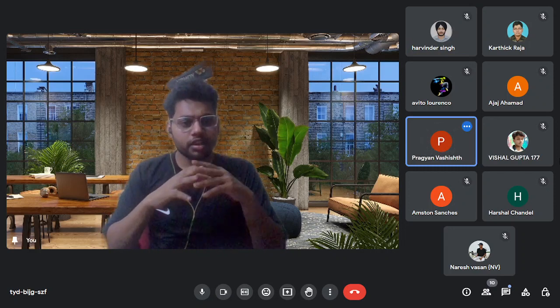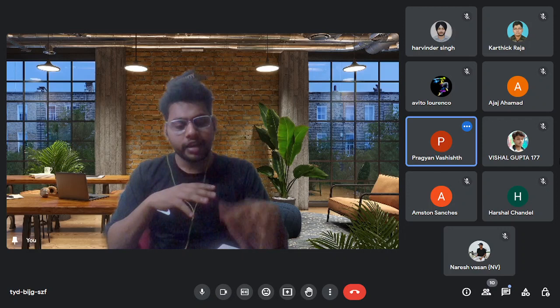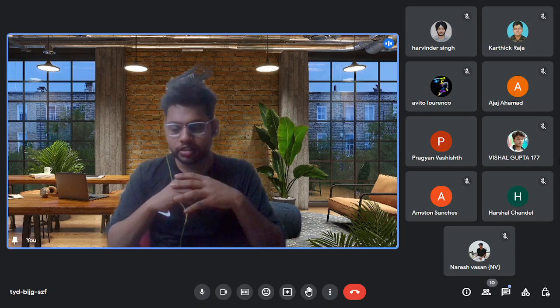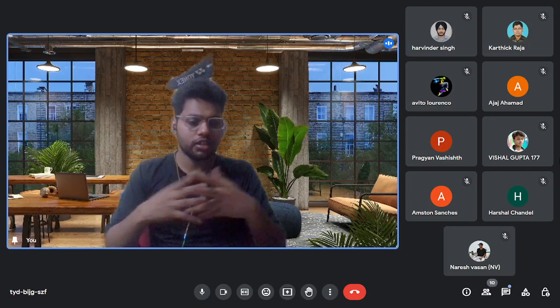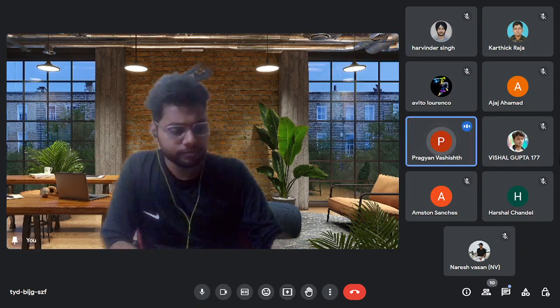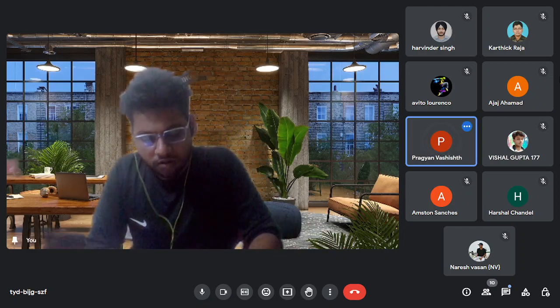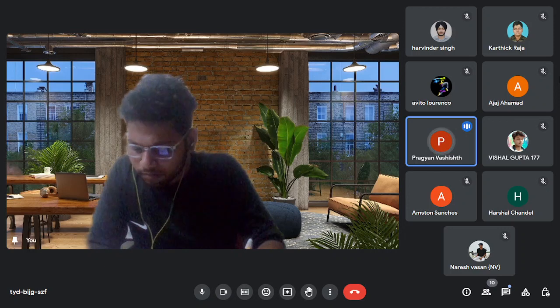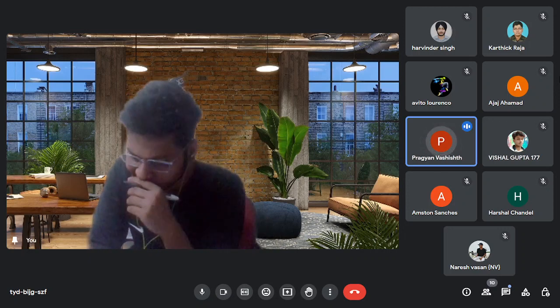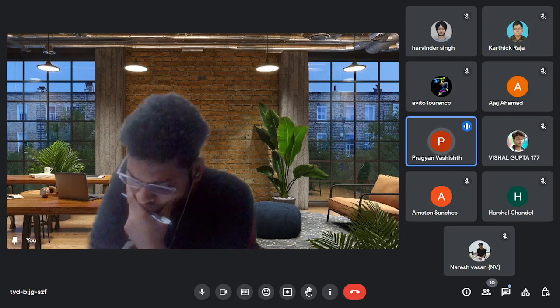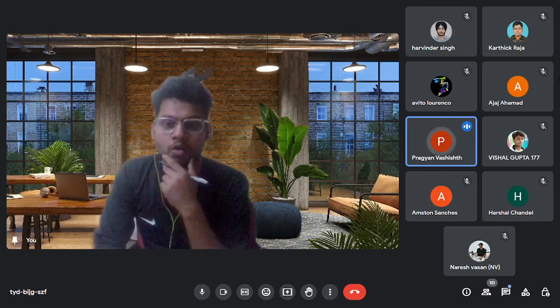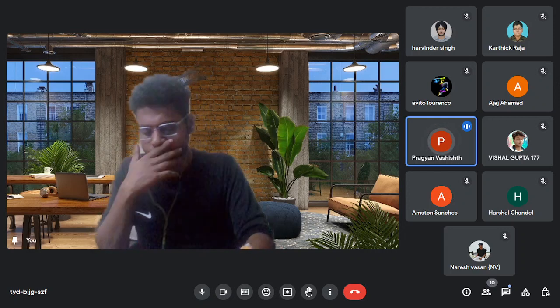Okay. So Pragyan, what you have just mentioned, magnetic crack detecting, radiographic testing, you have to also explain that. For sure. Let me start with ultrasonic testing. In ultrasonic testing, we have three parts: the transducer, the probe, and the display panel. Its working principle is on the basis of reflection of mechanical sound waves. It's just like sonar, like we use in submarines.